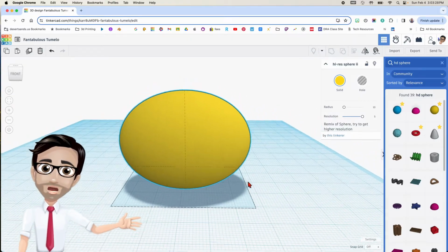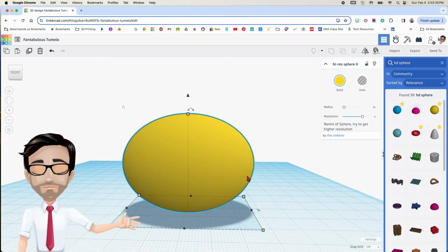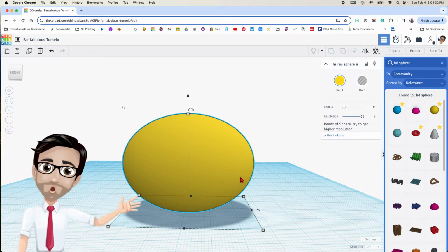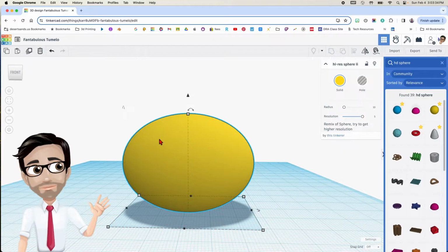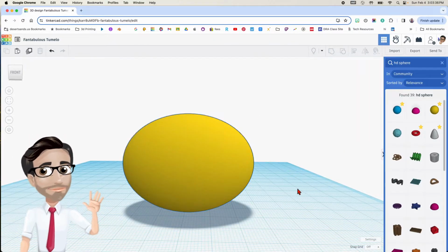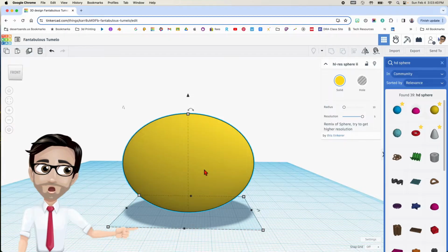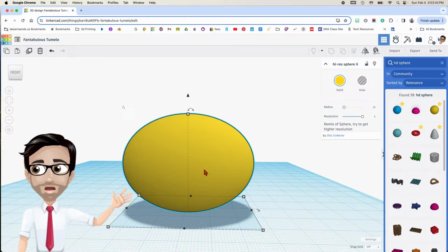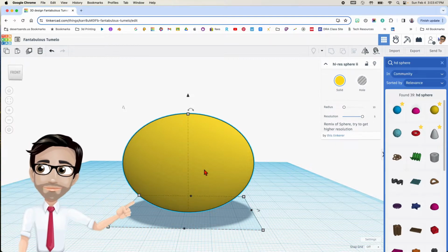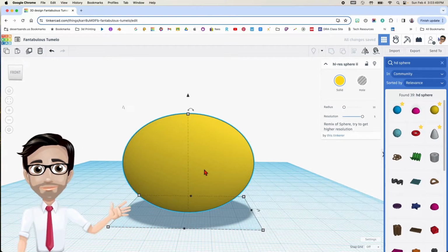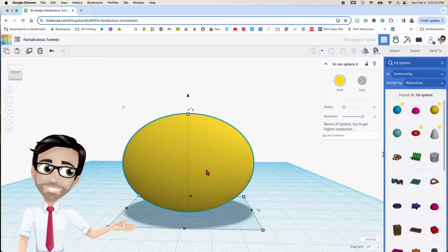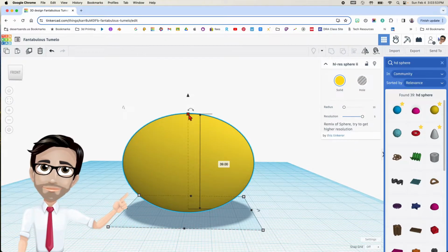But here's the part where it gets a little bit confusing. So make sure you do this next part without clicking on anything else. Like right now, it's fine, right? But as soon as you click this, you need to make sure that you don't click on anything else. So right now I'm going to duplicate. So Control D. Okay. Now I'm going to hit the Shift button and then drag this down.